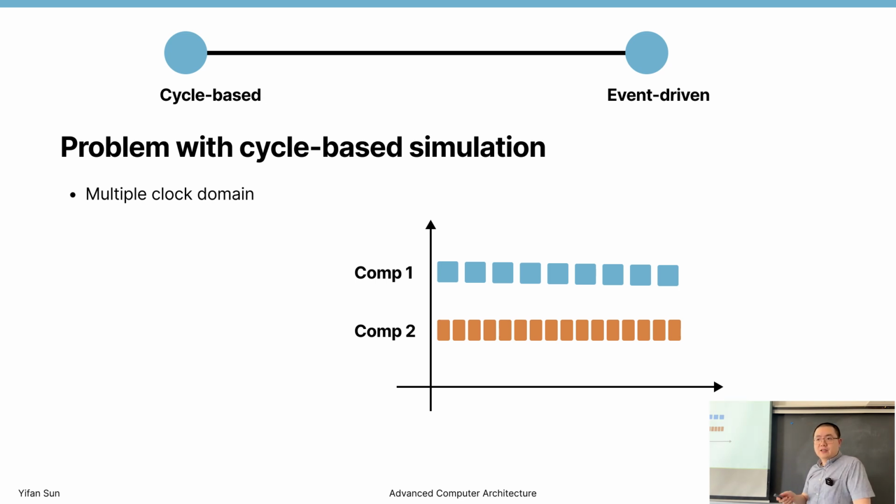This is a technology called dynamic voltage frequency scaling, or DVFS. Most chips have DVFS today, CPUs, GPUs, or any type of chip. For example, if you have a GPU in your computer, you don't want it to run at the full clock frequency while it's idle and the clock is still ticking.